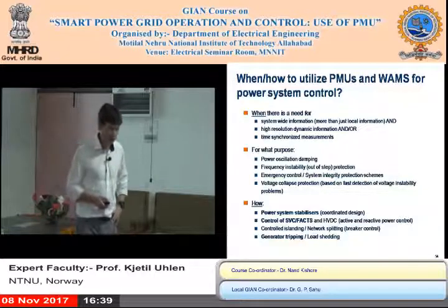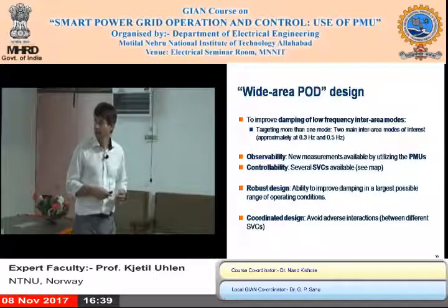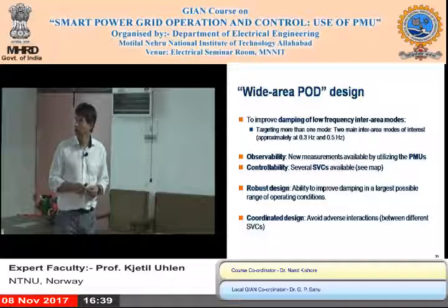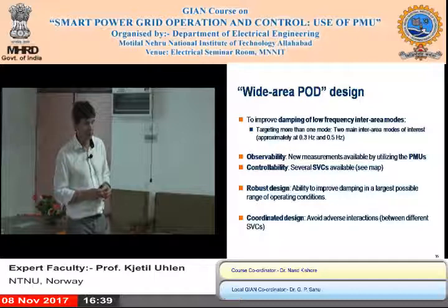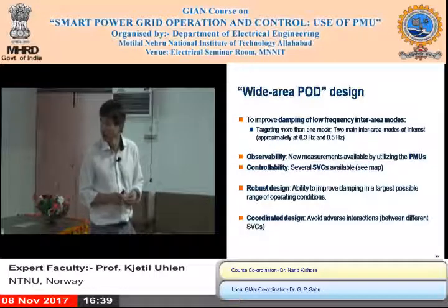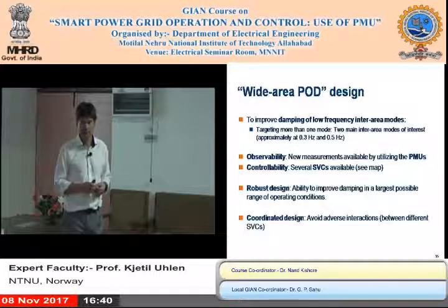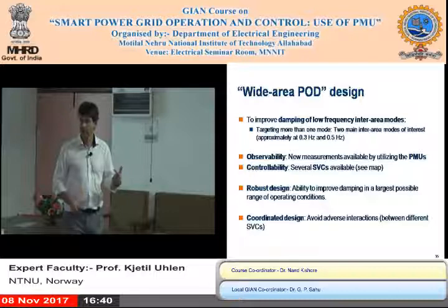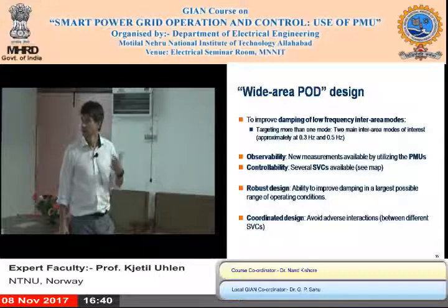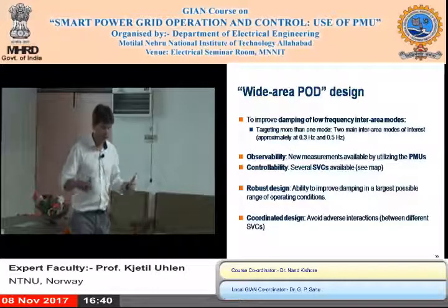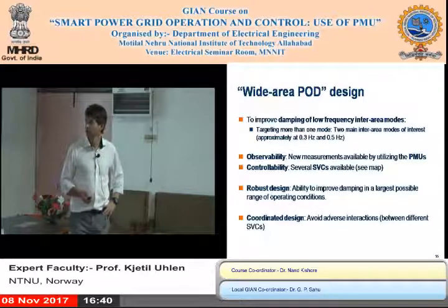The project that I have been involved in regarding wide area control was with the objective to design what we called a wide area power oscillation damper, and that is essentially a traditional power system stabilizer applied on a static VAR compensator, but with measurements from not just local, but from PMUs in the wide area.